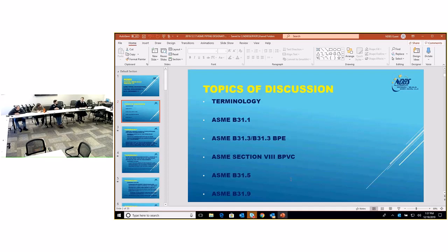The heat exchanger itself, according to Rockwell, and I have this in writing, does not require a PSV to protect the B side of that heat exchanger. Because when they did their risk assessment, they found that a single process failure did not exceed the pressure and temperature that the vessel could withstand. And there is no fire case to consider. In other words, they're not worried about a fire starting next to the heat exchanger and heating up the fluid that's inside the heat exchanger to a boiling point.